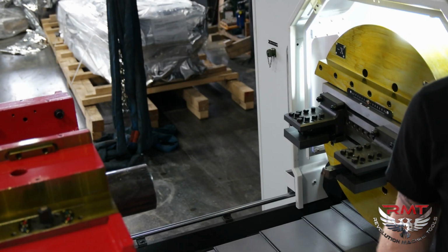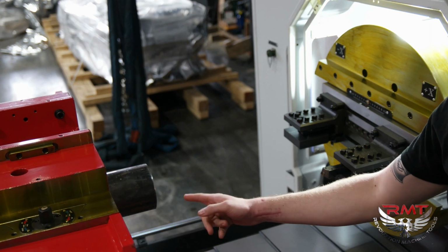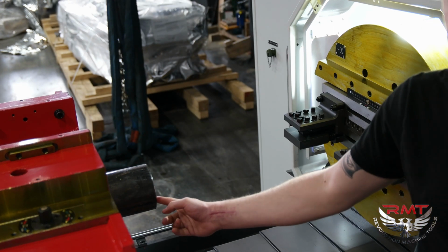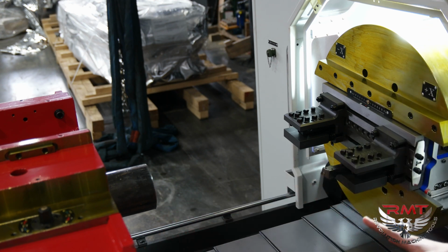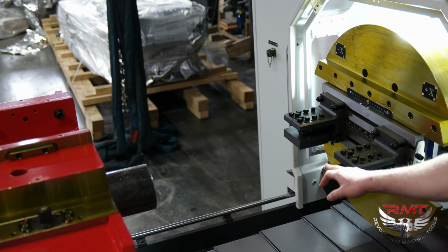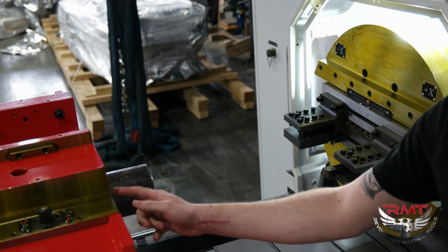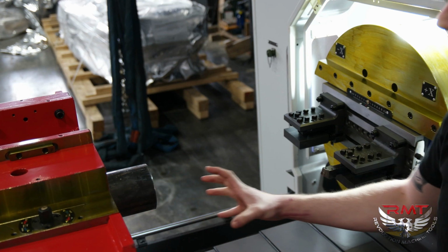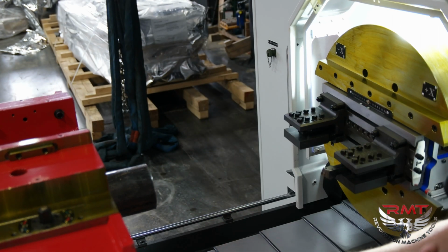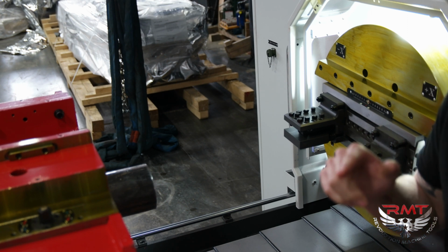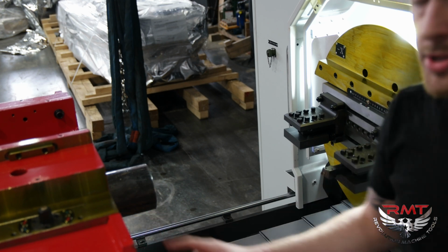Alright, so in this video, I'm going to be showing you how we're going to touch off our tool offsets and our G54 offset, or our work offset. Now, first thing, before we actually start cutting with our tool, ensure that you have properly adjusted your vises to be concentric with the spindle. Otherwise, we're going to be digging in really deep on one side and really light on the other side, potentially causing damage to your inserts or even breaking them. So that is very first.